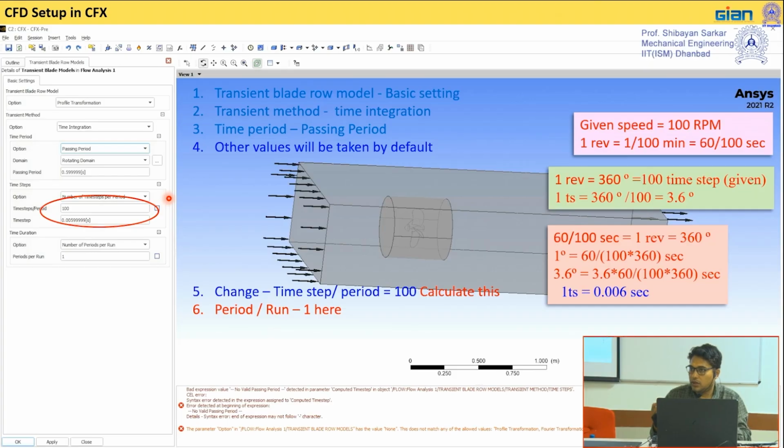Because of the load. We have already discussed the load, which is the electricity load. We are basically simulating the electricity load through a mechanical load, and if we increase the mechanical load, its speed will be reduced. If we decrease the mechanical load, its speed will increase. Say we fix that this particular turbine rotates at 100 RPM for a certain amount of load. Here we are not defining the load; rather, in the reverse way we define the rotation, because giving that value to the software is easier.